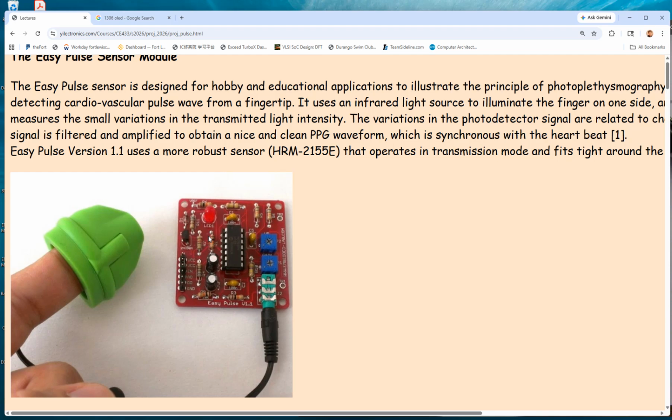So your power supply is 3.3 volts, powering up the chip. But the chip has cores, and it also has pads. We didn't show the pad circuit. The pads have the ESD diodes, a lot of buffers and digital circuits, and these digital circuits next to the pads of the IC chip use 3.3 volts as a power supply. That's very, very common. So 3.3 volts for these pad circuits.